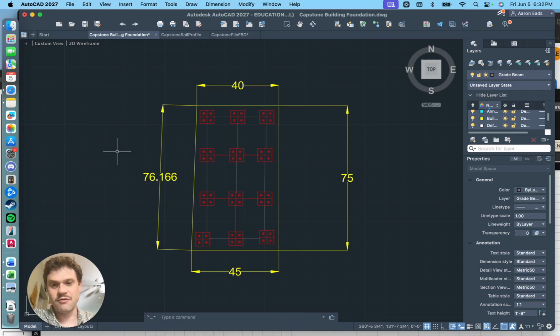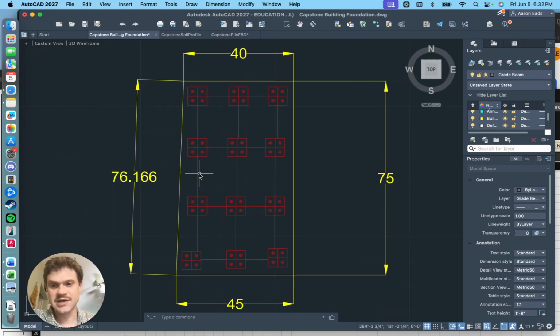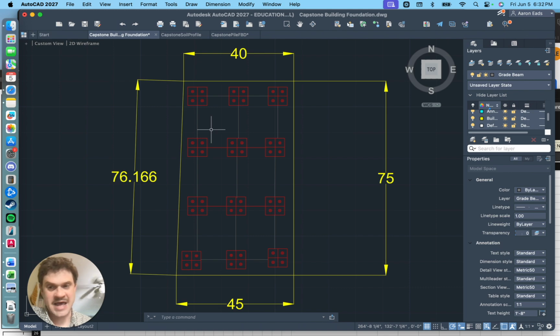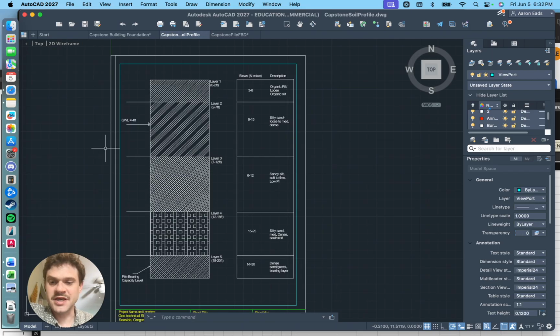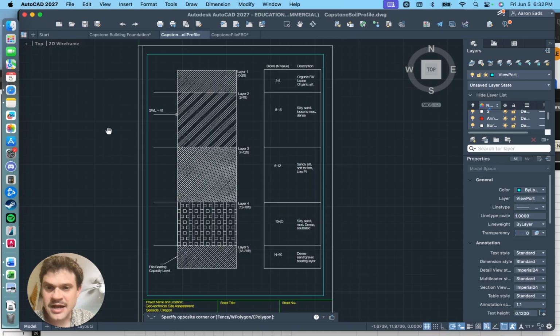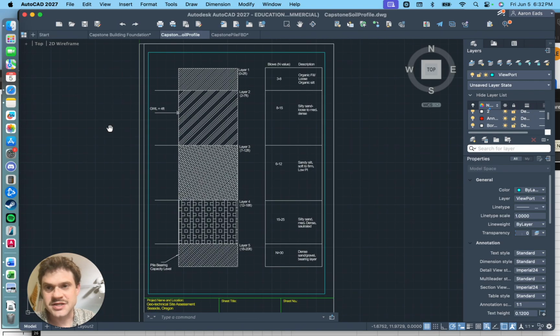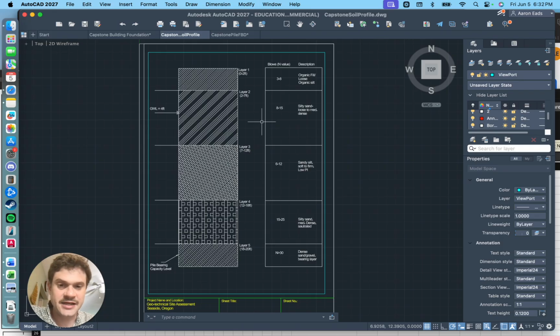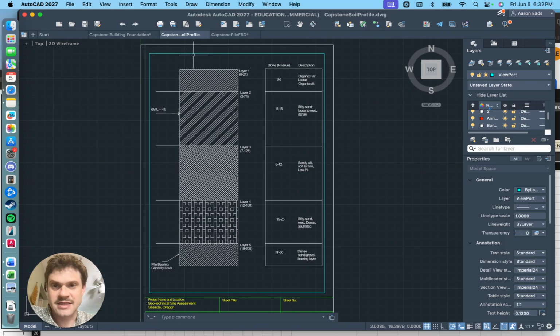But this is just kind of a rough outline of the piles, the rough layout, the beams interacting, connecting it all. And that's all based on the math. This is the pile analysis, soil analysis, the soil profile based on those numbers that I created, based on depths, your groundwater level, the density, the type of soil, things like that.